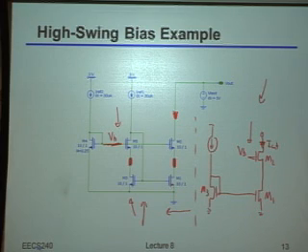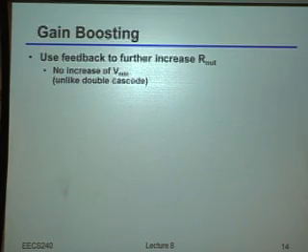Okay. So we talked a little bit about cascoding, but it turns out in modern technologies, even if you do a cascode, there's still a pretty, unfortunately, low limit in terms of the gain you can get. Because, for example, if I tell you that the gmro I can get from a device is something like, let's say, 10, then even with a cascode, I could maybe only get a gain of about 100, right? And oftentimes, I'm going to want open loop gains of something like 1,000 or even 10,000 or somewhere in that ballpark, okay? So it turns out there's one fairly, at least conceptually, simple trick we can play to make that happen, and hopefully do it in a way that doesn't run into headroom constraints.